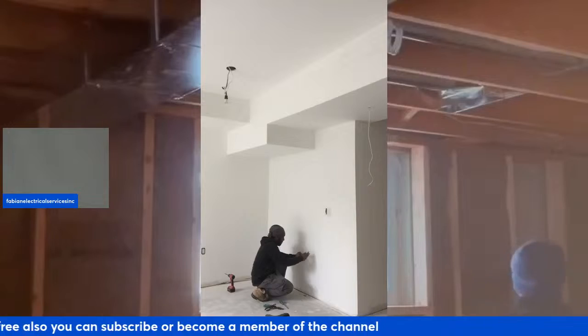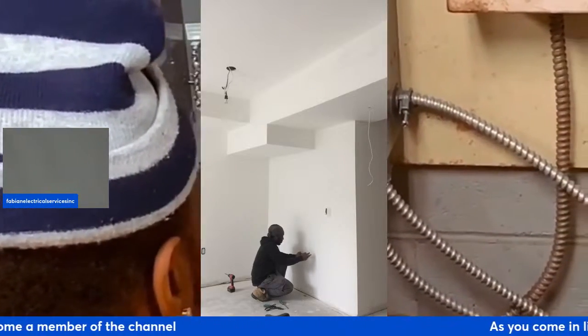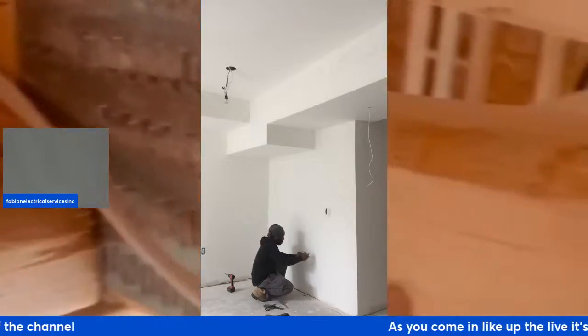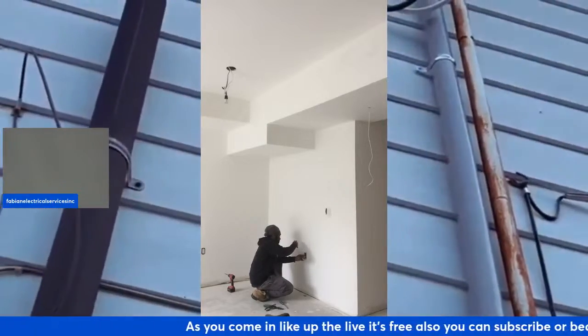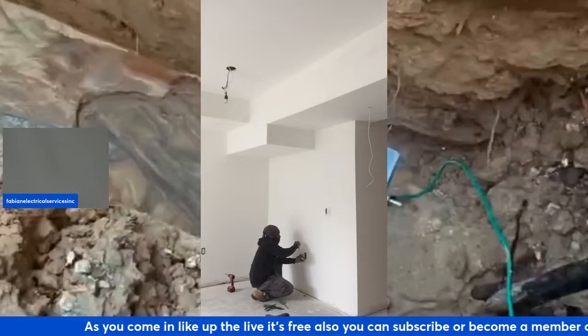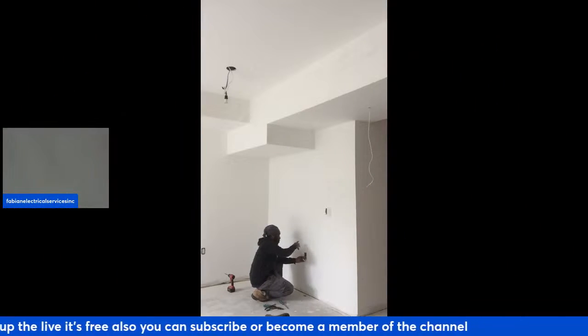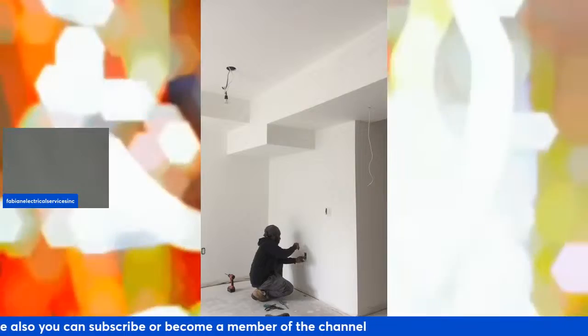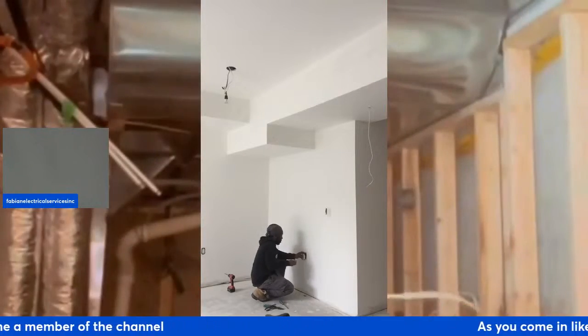This imbalance is caused by electricity taking an unintended path, like through a person or into water, like I mentioned before. It can be prevented by a GFCI outlet that senses even a tiny current difference, around 5 milliamps, and trips in a fraction of a second to prevent a severe or fatal shock.